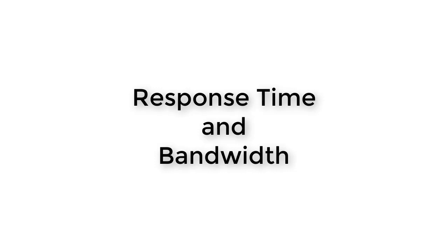The bandwidth of the sensor is expressed in hertz, that is, back and forth cycles per second, and tells you how fast the input can change back and forth and still have the output read well enough. Well enough is often considered to be less than 3 decibels of the amplitude of the motion lost.